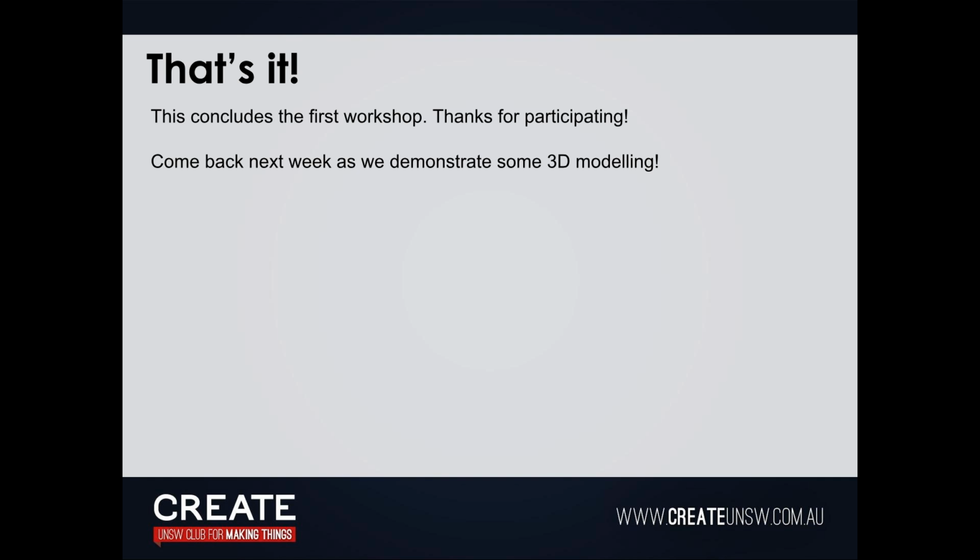Yeah, but like I said before, you don't want to delete any bodies. You just want to hide it so it doesn't mess around with your timeline. Like we mentioned, the timeline's down here. If you change something that's referencing something else, it will mess up the whole sequence. So you just right click it and hide it, right? Okay, anything else? You can do revert.